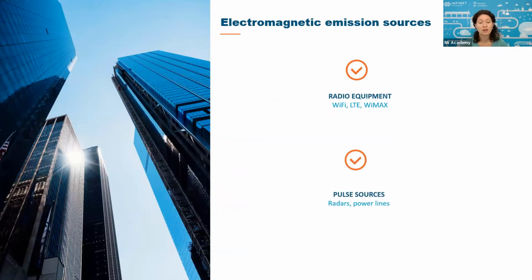Another type of electromagnetic radiation source is the pulses coming from unknown sources, for example, from radars and other radio equipment operating in a different spectrum, that will be seen as noise. What I want to mention is that wireless devices should not be placed near power lines. It is necessary to install the devices at a distance of at least 100 to 150 meters from power transmission lines having a voltage higher than 35 kilovolts.